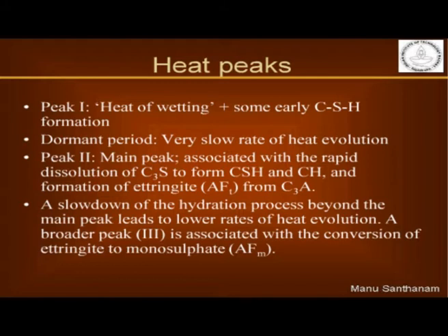and I also form ettringite, which is actually a product of the reaction between C3A, that is your tricalcium aluminate, and the gypsum that is added in the cement manufacturing process. Please remember, we added this gypsum in the cement manufacturing to control the rate of C3A hydration. So in the presence of this gypsum, it produces this ettringite, which is actually a calcium sulfoaluminate phase. I'll come back to the actual reactions later, so you can actually see.